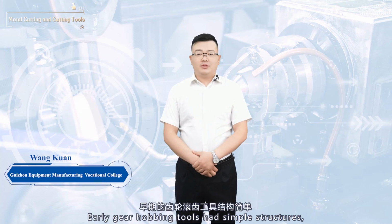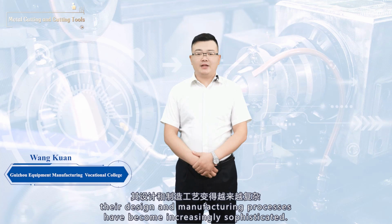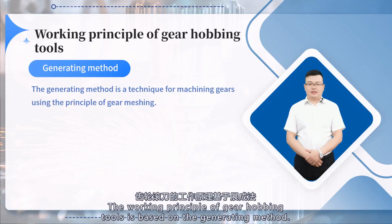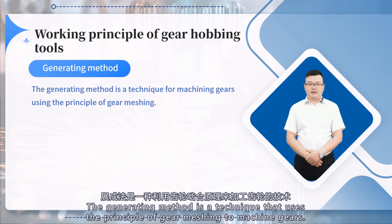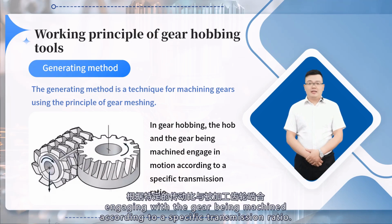Early gear hobbing tools had simple structures, but with the continuous advancement of industrial technology, their design and manufacturing processes have become increasingly sophisticated. The working principle of gear hobbing tools is based on the generating method. The generating method is a technique that uses the principle of gear meshing to machine gears. In gear hobbing, the hob functions like a helical gear with a large helix angle, engaging with the gear being machined according to a specific transmission ratio.